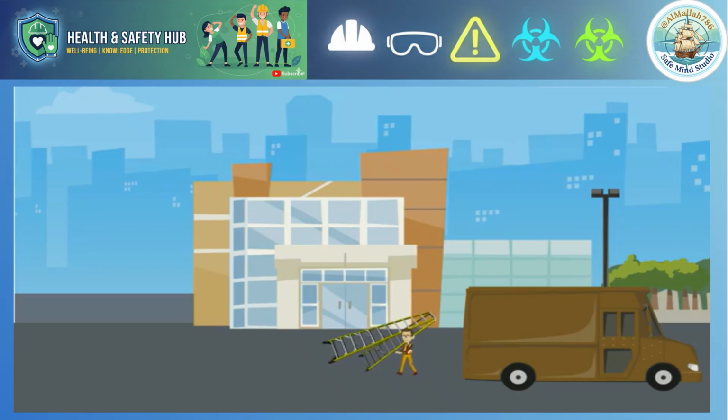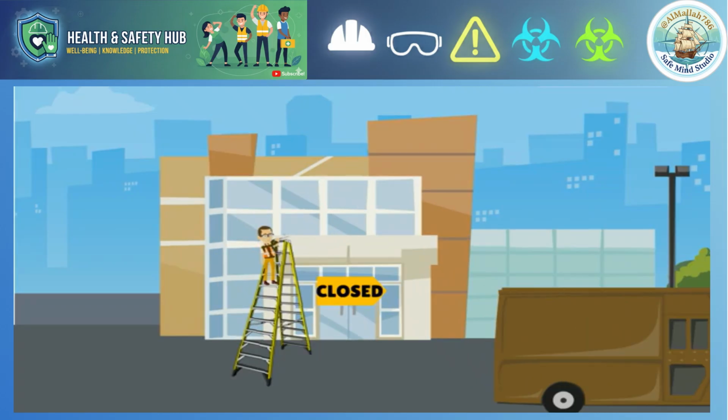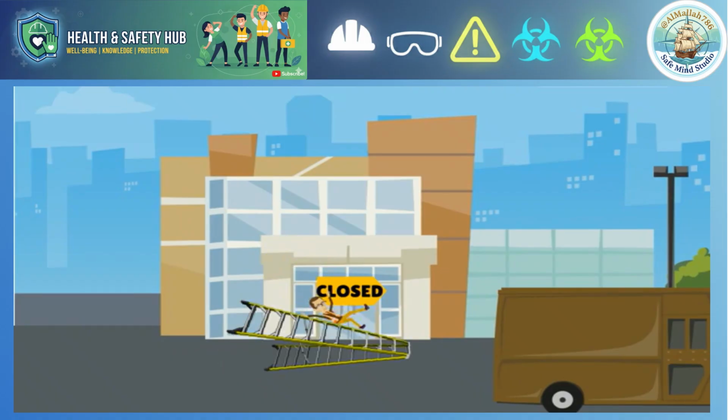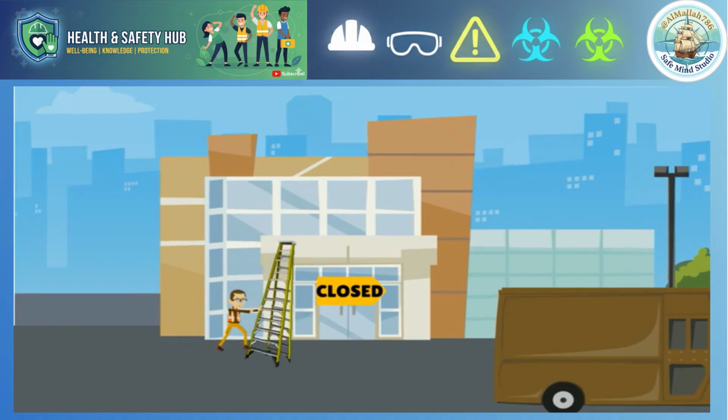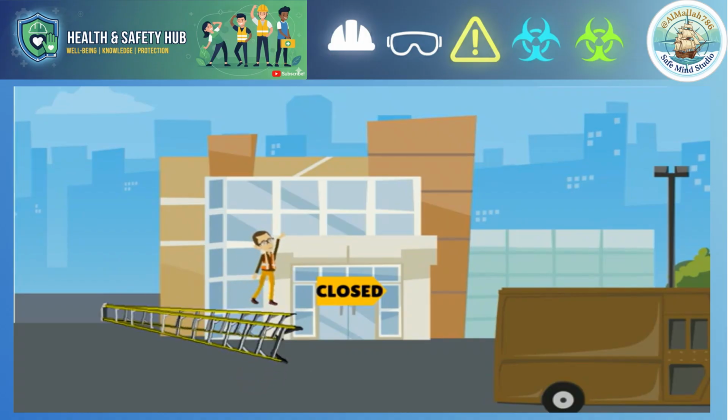Place a stepladder at right angles to the work, with either the front or back of the steps facing the work. When working from a stepladder, keep your hips within the two vertical rails. Reaching too far to the left or right could cause the ladder to topple. Never lean a closed stepladder against a wall and then climb it, because it can easily slide out from under you.